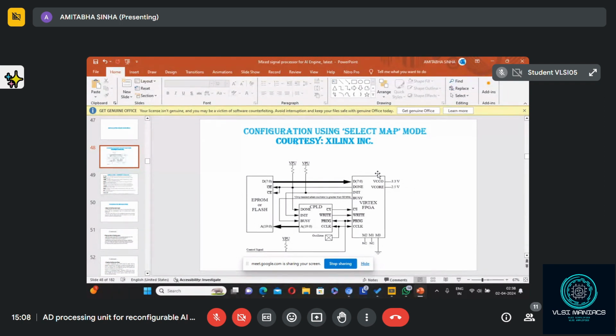Normally in the CPU, this CS bar is not there, but in the memory and controller, this kind of device, you will find this chip select bar. When chip select bar is low, then the chip will be selected. If the chip is selected, then only any operation will be performed, not otherwise. It will be totally disabled. So to enable this FPGA chip, this CS bar should go low.